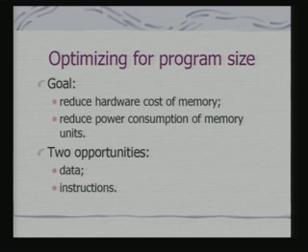Related to this is the problem of optimizing for program size. If you are looking at a node, a computation, I need to optimize for the program size. Now, the other point comes in. Just try to understand these trade-offs. In the previous case also, we looked at the trade-off with regard to loop unrolling vis-a-vis loop nesting. We are trying to look at function inlining vis-a-vis optimization of the program size. If I am doing function inlining, I cannot do optimization. Okay. But I need to do an optimization because I would like to use minimum memory, because that also is a constraint for a design.